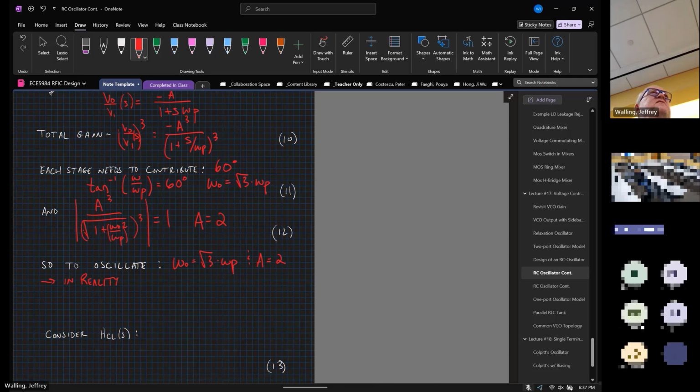Basically you give it conditions that would cause exponential growth in the oscillation, and then once the oscillator reaches a sustained oscillation, it tends to have feedback conditions that cause the gain to drop, and it reaches a steady state where it's exactly meeting Barkhausen's criteria. So you give it a little bit of extra oomph, it starts up, and then it will drive itself to sustain the oscillation.